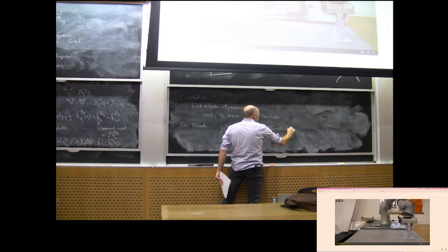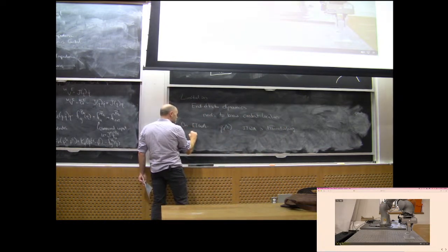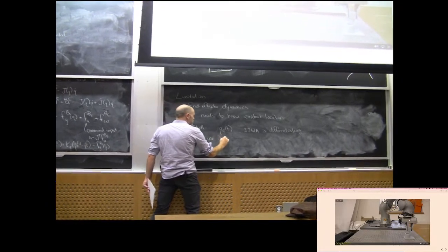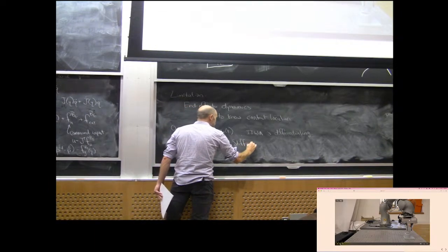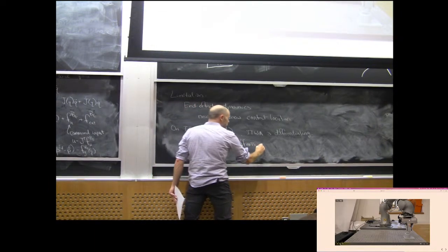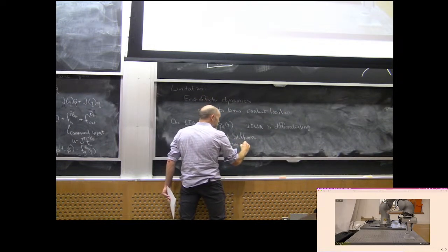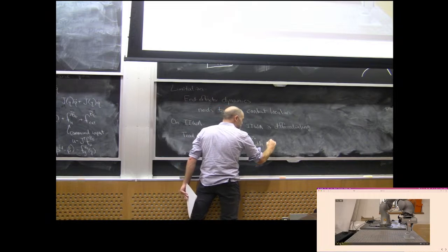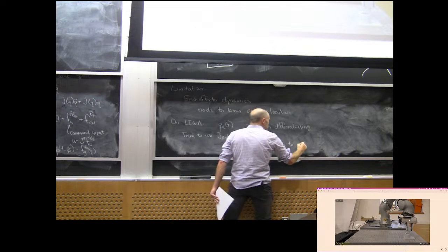We tend to do joint stiffness control. Despite the elegance of the Cartesian stuff, the joint stiffness is more robust to unknown contacts, I think, or a more reasonable response. Principle of least astonishment, if you will, in responses to unknown contacts.